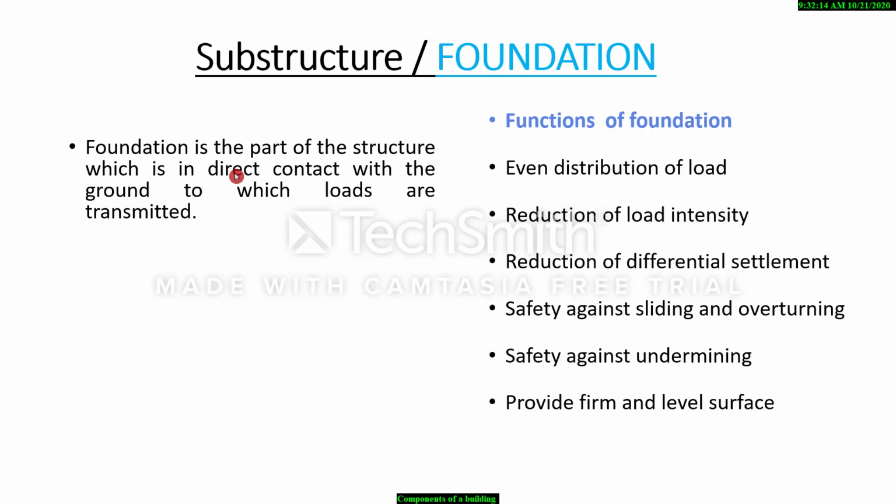The various functions of foundations include: it helps for the even distribution of the load of the building, to reduce the intensity of load by spreading the load to a higher area. It reduces the differential settlement. Differential means, suppose a building is loaded, it will be having a uniform settlement. There won't be any tilting of the building. It provides safety against sliding and overturning. That means the building won't move towards the sides or overturn.